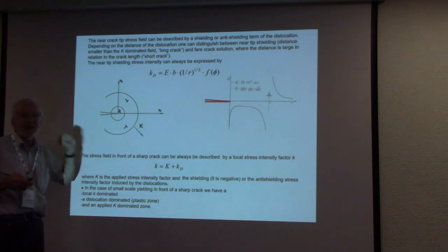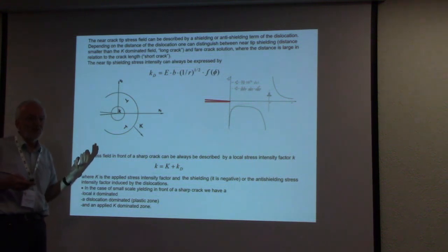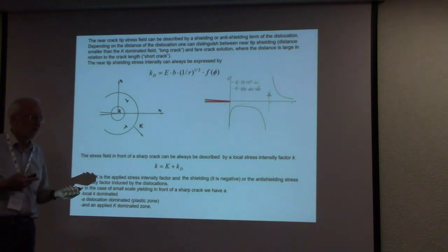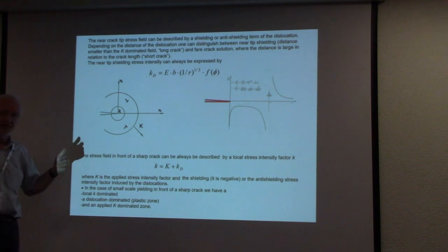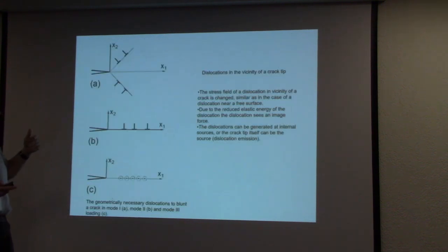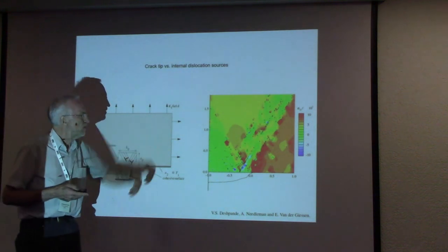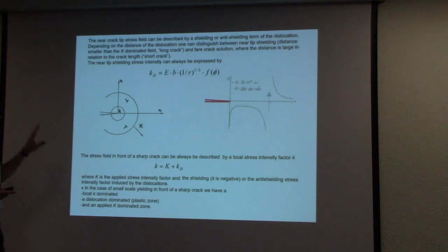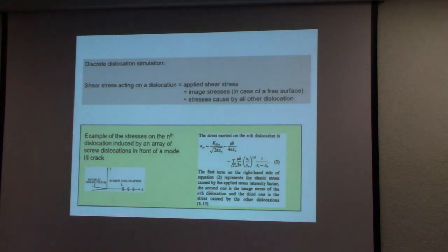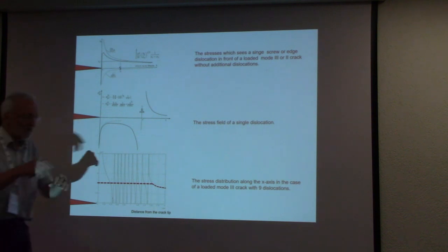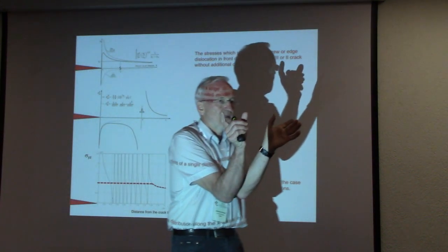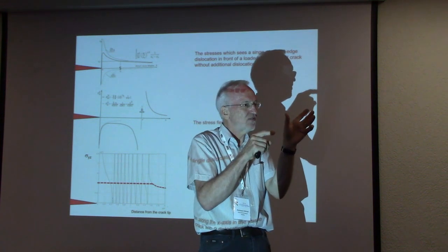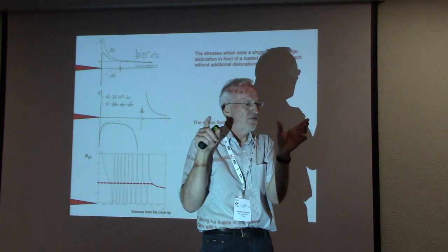And the problem is that so many dislocations are there, and only, I would say, in 2D we can treat about 2,000, 5,000 dislocations. What you have seen here, for example, are a few hundred, but in principle, a few thousand would also be possible in 2D. In 3D, you have to separate the line into small pieces. There also exists an exact solution for the stress field of these small pieces of dislocation.